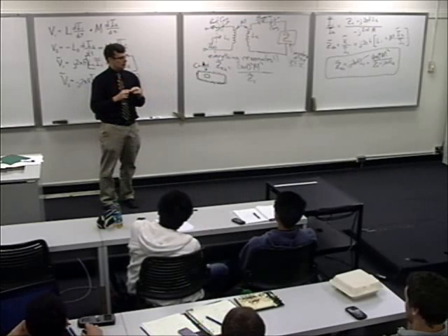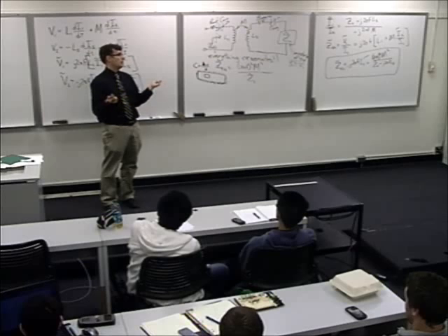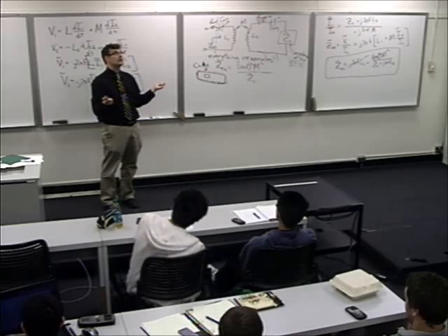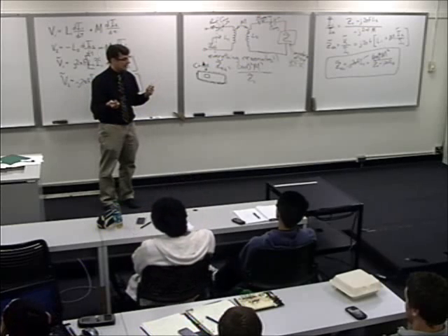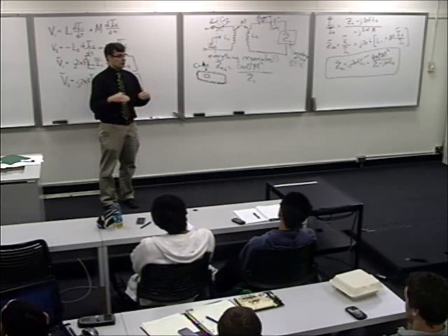You could surreptitiously install a power amplifier on the reader so that the current is much bigger. But even then, you could multiply the current by a factor of 8, and you would only double your range. In other words, power would go up by a factor of 64 input power into the device, and range would double.